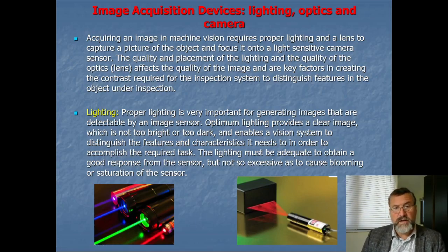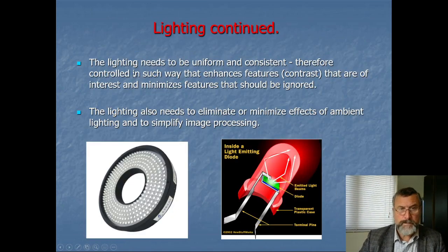So we need some adequate lighting here. We don't want saturation of the sensor, and we can get lasers and LEDs, all sorts of different wavelengths, of course. We're trying, as it says there, by means of some good lighting, to make it easy to distinguish the features and characteristics of interest from the background, really.